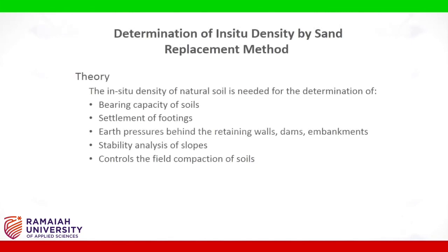The in situ density of natural soil is needed for the determination of bearing capacity of soils, settlement of footings, earth pressures behind the retaining walls, dams, embankments, stability analysis of slopes, and it controls the field compaction of soils.